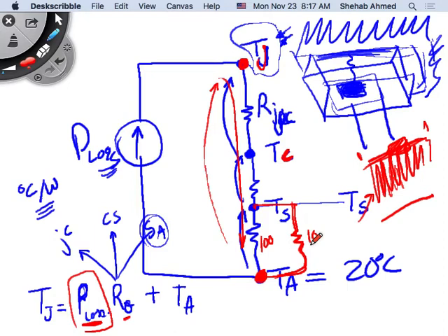So that's why we would model a better heat sinking process as a resistance in parallel with the sink to ambient resistance. As a first degree, right? So maybe you find a full equivalent to that if you want to go into more detail, but just as a simple approximation, that's what it is basically.